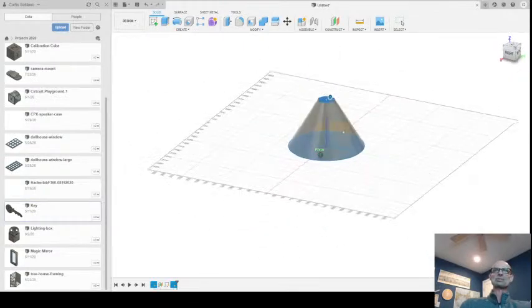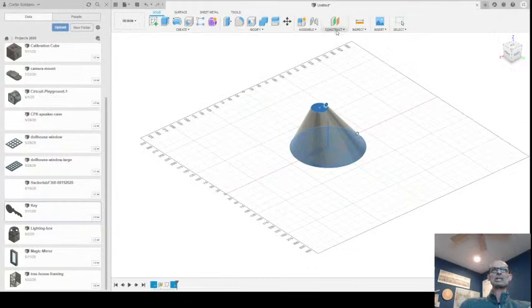Maybe there are other ways to script it or what have you, but without the creation of a construction plane at a different altitude, I would have had nothing to sketch against. Maybe I could have created a square that was 150 millimeters and then try to create a new sketch on that square's face, and then turn the square off so only the face of that square was there, and then use circles. There might be other complicated ways to do it, but that is one way to use construction planes.